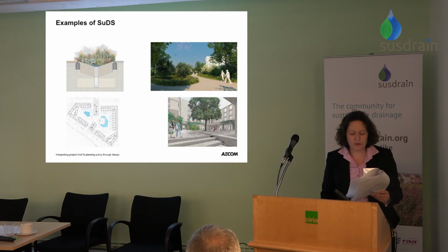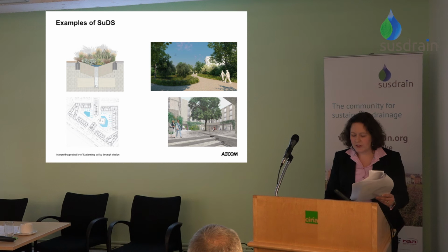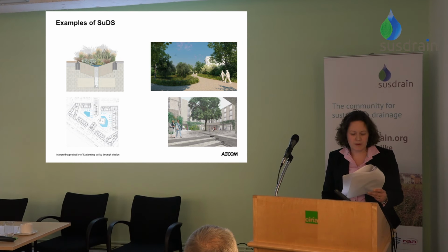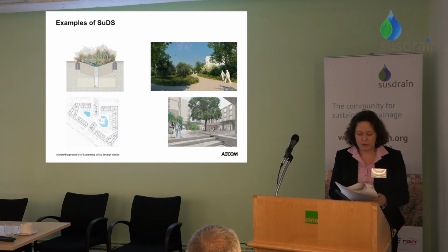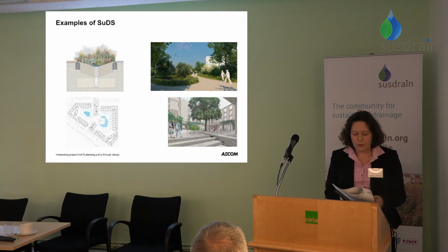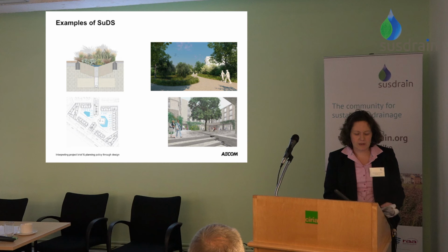Controlled surface flooding was used on several plots. The example here is from Lot 3 and shows the areas in blue which were designed to hold water in significant rainfall events. In Lot 2, rills were incorporated into the design. Attenuation was also provided in blue and brown roofs and impermeable pavements across various lots. Whilst attenuation crates were incorporated in some of the designs, they were the least preferred solution of the design team, the university and the City Council.